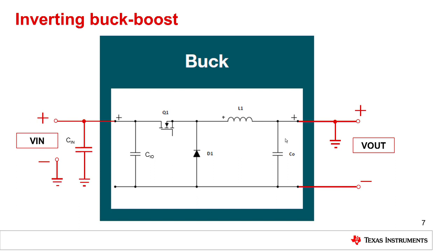And we do that very simply by reassigning the input and outputs. The input voltage still goes to the same place as it did in an ordinary buck with respect to the system ground, but now the output voltage of the buck is actually grounded, and the common ground terminal for the buck regulator becomes our negative Vout. And that's essentially all we need to do in terms of the mechanics of converting a buck regulator into a buck boost.